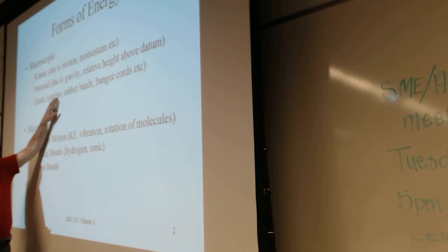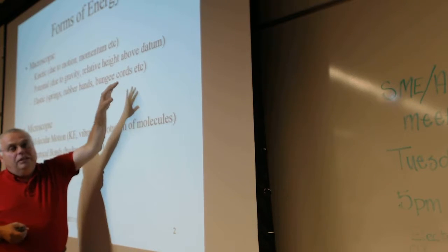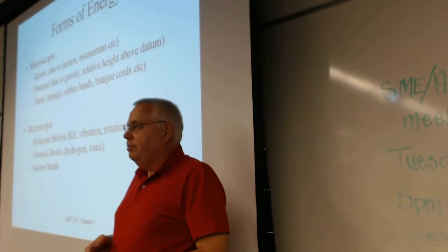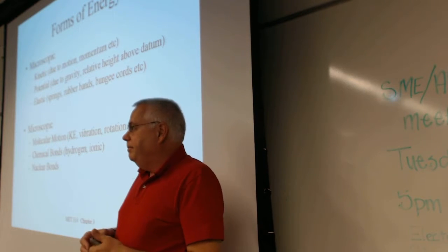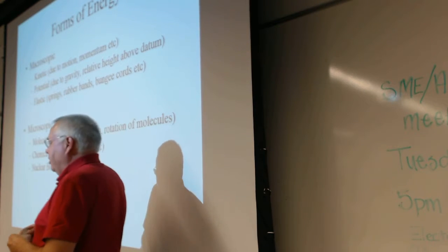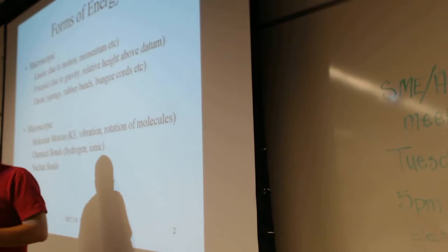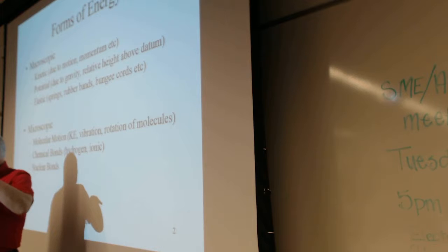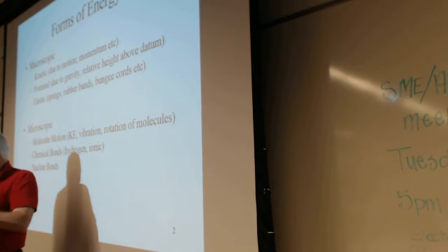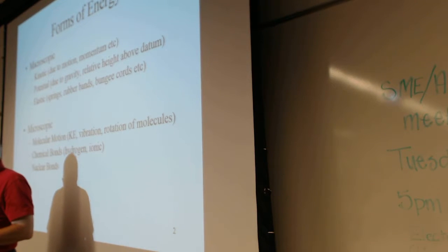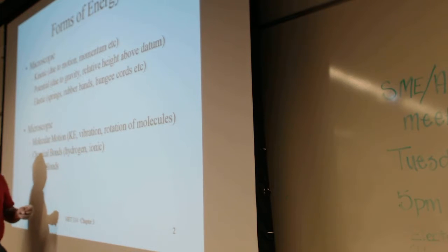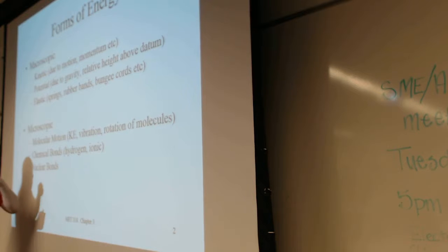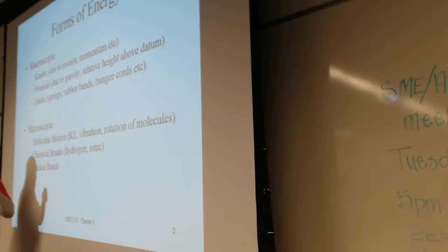There's elastic energy that can be stored. Springs store energy, 1/2 kx squared for a linear spring. And there are nonlinear springs. Virtually all of your cars have nonlinear springs. They're nice and soft if you have a small motion, but if you hit a big bump, suddenly they get stiff so that you don't just whack your way all the way down to the stops. You can also store energy in a rubber band: pull on it, force times distance, and it'll give that back to you.